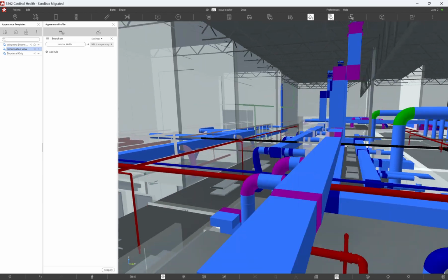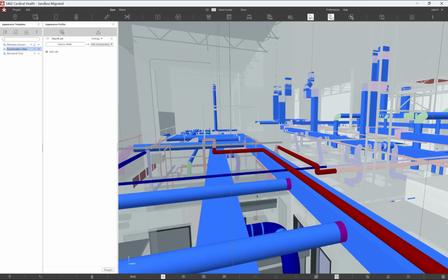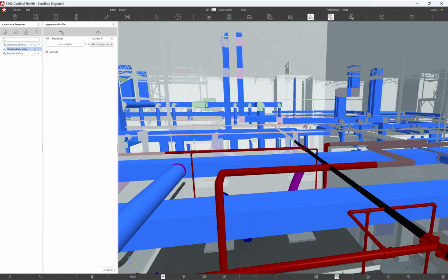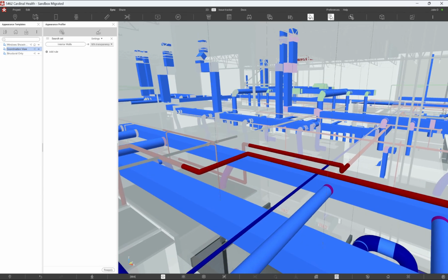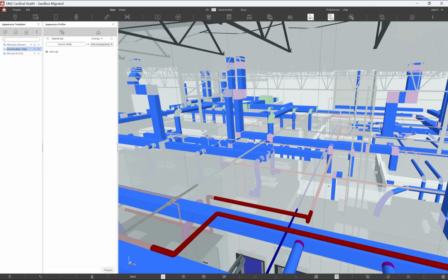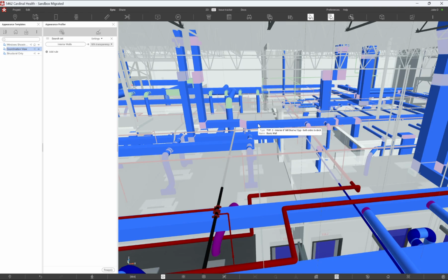Yeah, so all the walls are transparent. It just makes it easier to view, so you don't need to constantly worry about hiding walls. You can just sit in here and look straight through the walls to see if there's any ducts, conduits running through the wall, and you need to make sure it's in the correct location. And even after the template is created, you could go through and change from 50% transparency to hiding it completely, save and update